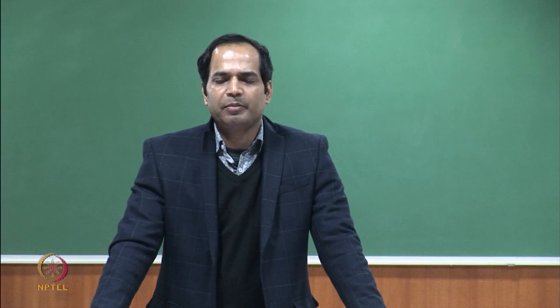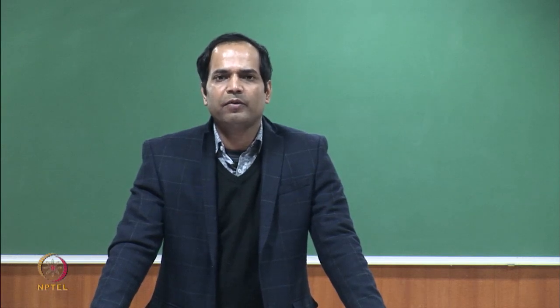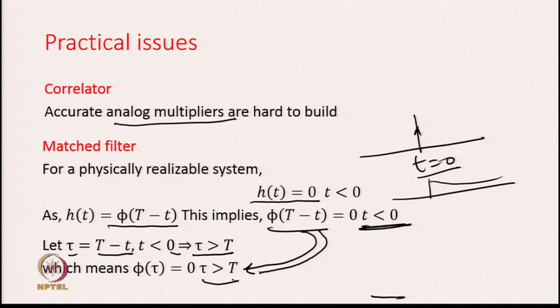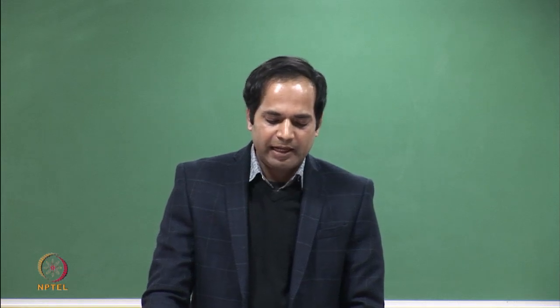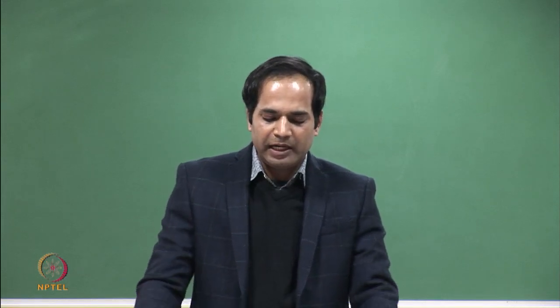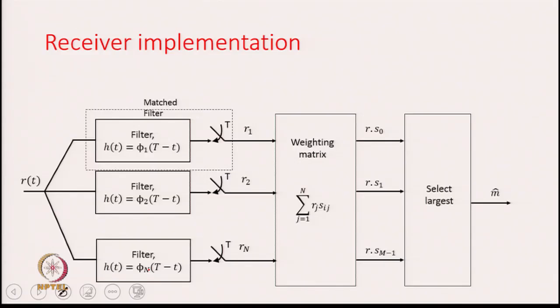So, the physical realizability of the matched filter puts some restrictions on the kind of orthonormal functions that this system can deal with. Okay, let us move ahead and let us see now the complete full blown receiver implementation. Maybe it is too far fetched because we have not yet studied noise and so on, but let us see how the full blown receiver looks like,